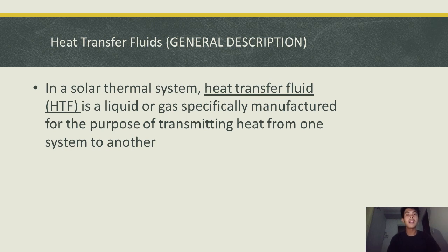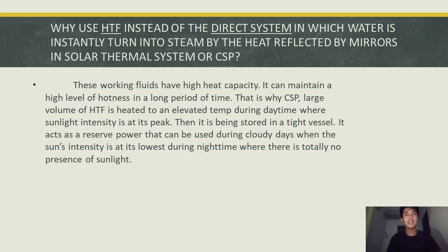Although heat transfer fluids technically can be used at temperatures close to their pumpability points, many fluids, especially petroleum-based fluids, lose much of their heat transfer ability and efficiency when used close to their pumpability points.